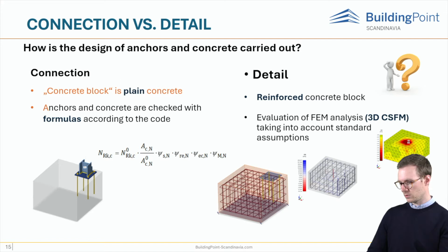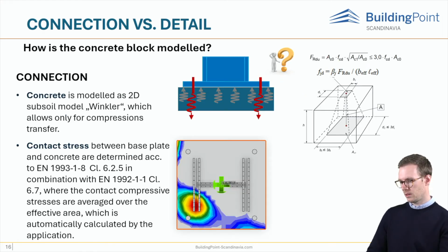And the block is reinforced, and the block and reinforcement are modeled as finite elements, and the 3D CSFM is utilized. Second one, how is the concrete block modeled? Well, in the connection application, the block is modeled as a 2D Winkler subsoil model, which only allows for compression.